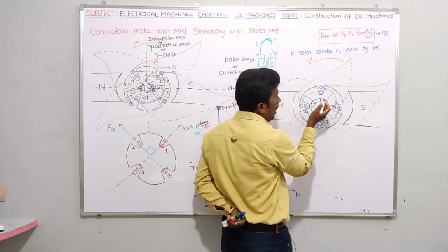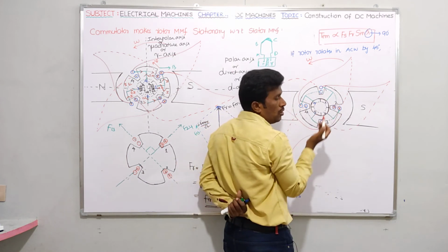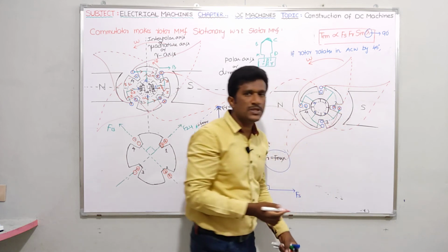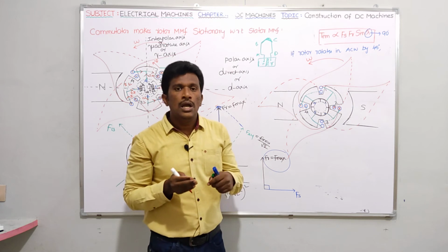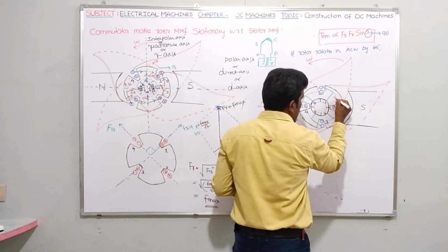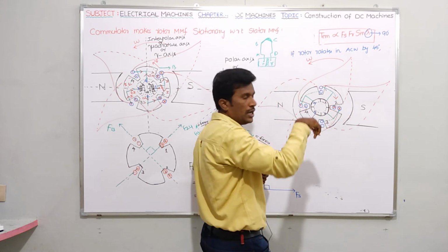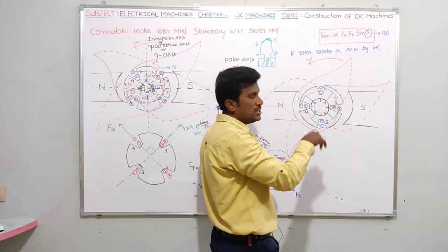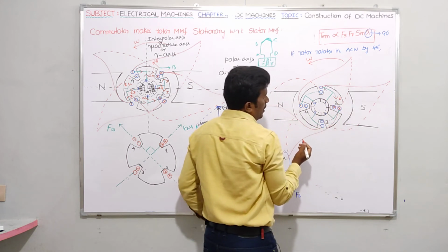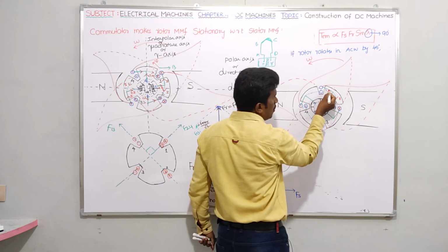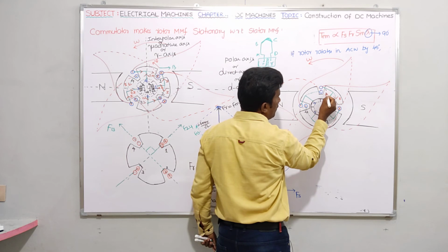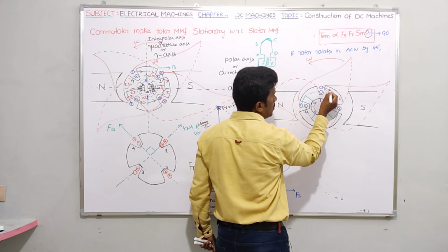So now please tell me direction of current into the segments, guys. Very simple. Do we have any current from this slot 1? No. And what about this? If you see slot number 2, guys, we are getting cross. Cross means direction of current entering into the board. Into the board means arrow mark should be like this. Not coming from the board, it is into the board. So this is what I can say, I value. Do you have any current here? No, 0 amperes. So obviously total current will be coming from the segment number 1, I amperes. Here I can say 0 amperes, there is no need to show 0 amperes here.